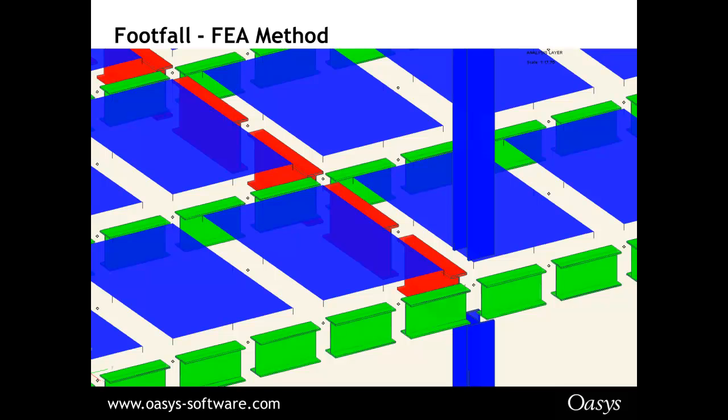But for steel concrete structures, quite often you want to start adding in the offsets. You do start to model some composite action between the floor slab and the beams, and this makes a huge difference to the response values. You also tend to restrain the structure so that you avoid horizontal vibration modes. If it's a floor slab, maybe if it's a bridge too, but if it's a staircase, the horizontal modes tend to be a necessary part of the vibration of a staircase, and so the restraints will vary. All these simplifications you add in will vary depending on what type of structure you've got.